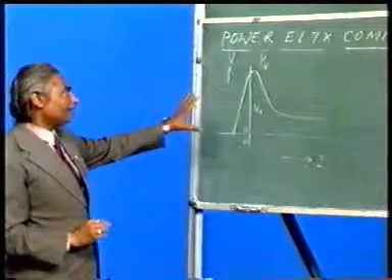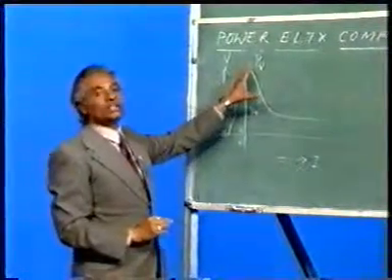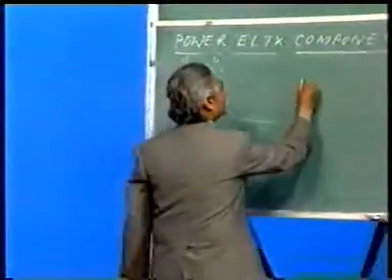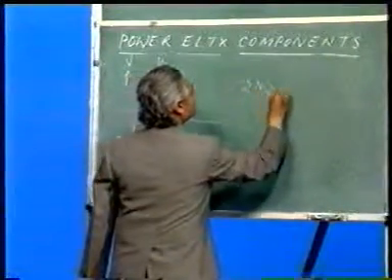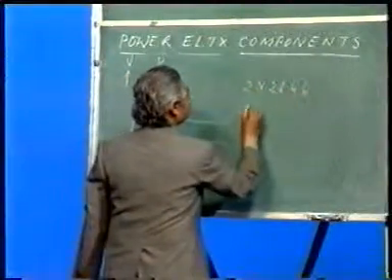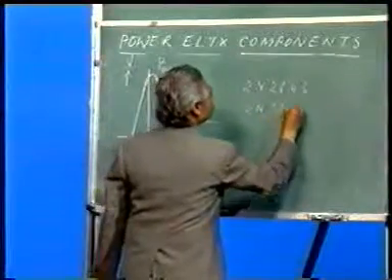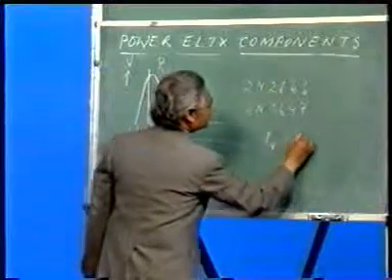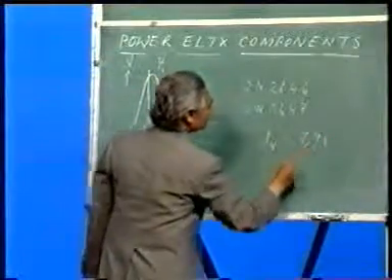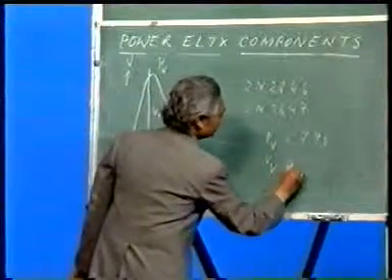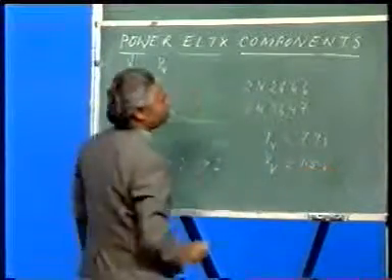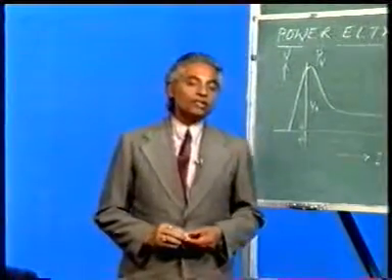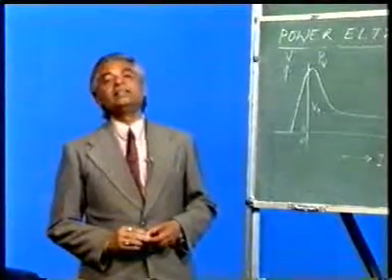So the valley voltage and the peak point voltage are very, very important specifications of a UJT, and commonly used UJTs are 2N2646 and 2N2647. For these, the peak point voltage is 7.9 volts and the valley voltage is 1.5 volt. So with these specifications and this type of testing, you can choose your UJT and connect it in any circuit.